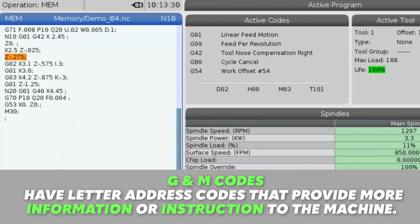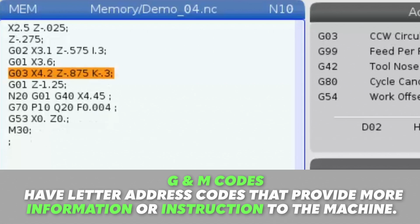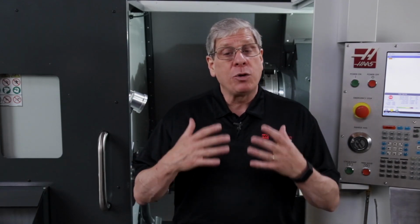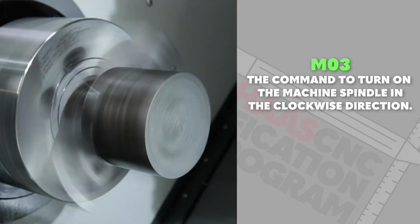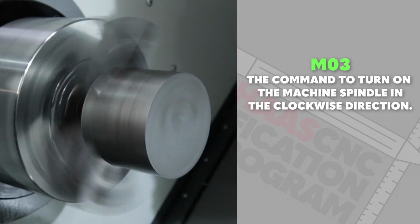Both G and M codes can have letter address codes that provide more information or instruction to the machine. These letter address codes are letters and numbers that come after the G or M code that give the machine all the information it needs about a particular function. For example, the code M03 is the command to turn on the machine spindle in the clockwise direction, but it doesn't tell the machine what speed to rotate the spindle.